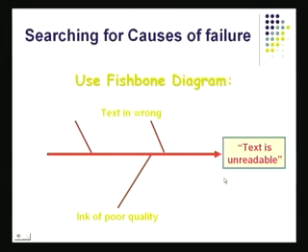And many times, of course, you'll be able to fish this out. You'll be able to figure out what caused what if you construct the fishbone diagram, and you do something in a very disciplined way that is called brainstorming. The only thing you do there in brainstorming is you do not control the number or the diversity of the ideas that come up that are given by people. This is something you do not try to control or do quality check on. Let it pour out, and then hopefully some gems will also emerge as a result of brainstorming. So the fishbone diagram is a great tool to do brainstorming and figure out many different ways by which this failure could have taken place.